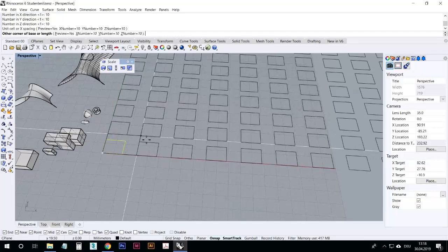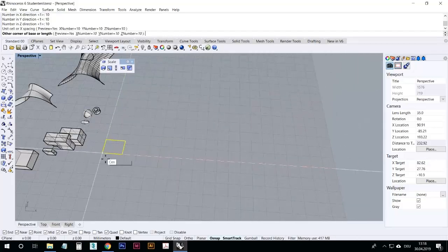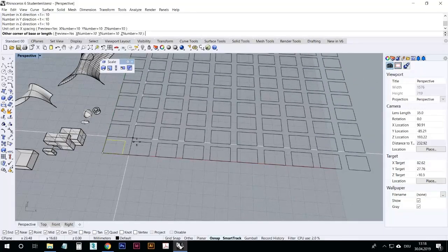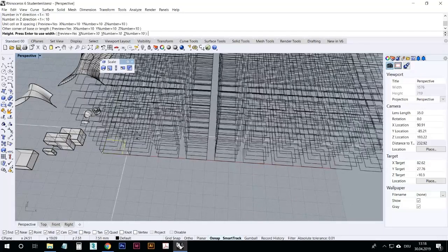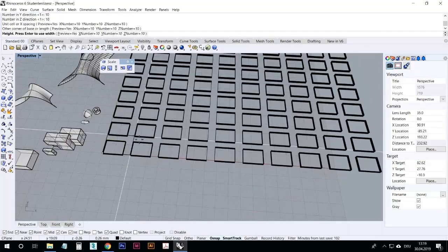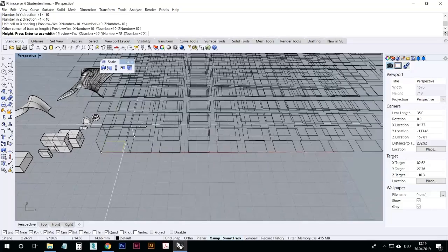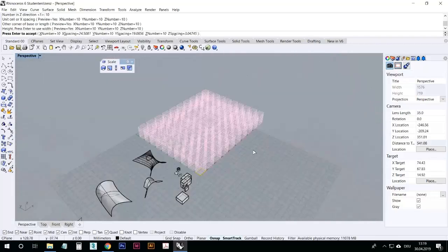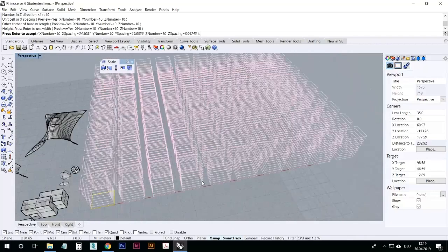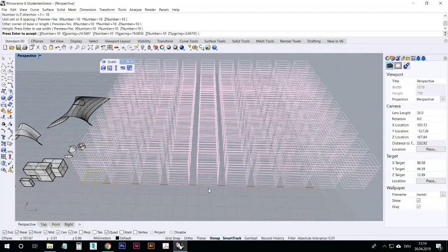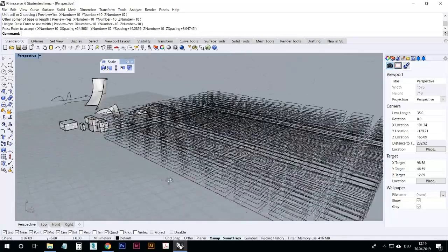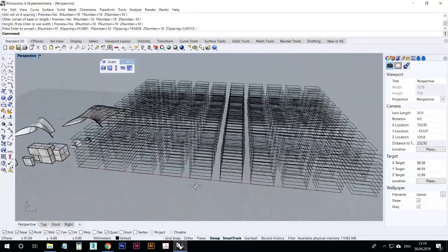Like that. You see, if you click then somewhere where you start and where the end position is going to be, you see a preview already. Let's say it's like that. And then it also, since I typed in 10 in Z direction, it's going to ask me that as well. So then I can turn it into a big grid like that. And it turns in actually pink. It's because it's a preview. You have to confirm that you want to have this. Otherwise you would just press escape. You know, so enter once more, and then you have all the curves built like this.